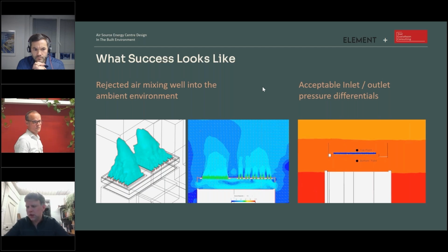When it comes to noise, if we're overworking the fans and the pressure differential is outside of the operating specified differential from the fan supplier, we might find that we're starting to encourage far more noise than is acceptable. So what we're looking at is these suitable pressure differentials above the top of the heat exchanger and below in the intake as well. Next slide, please, Joel.